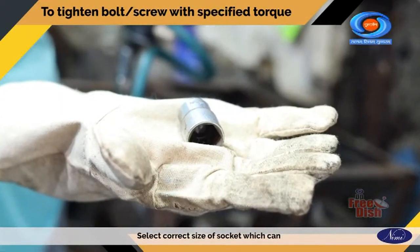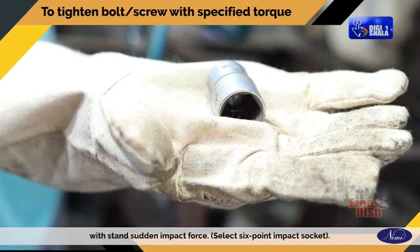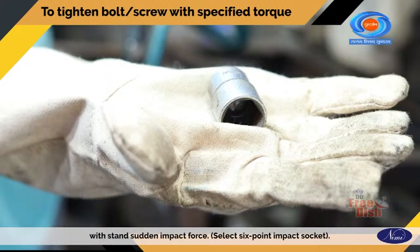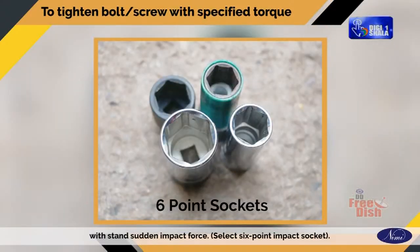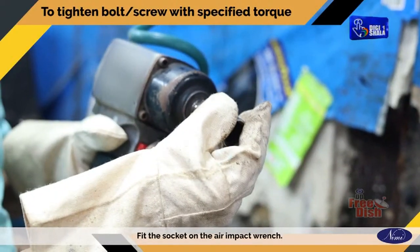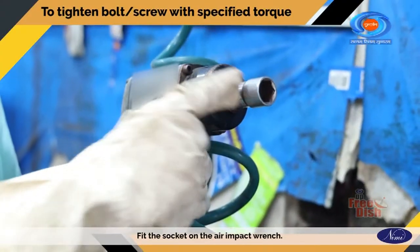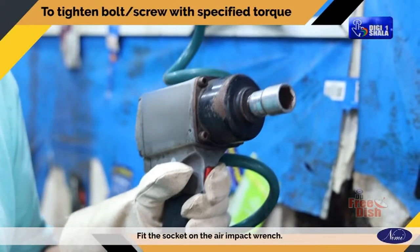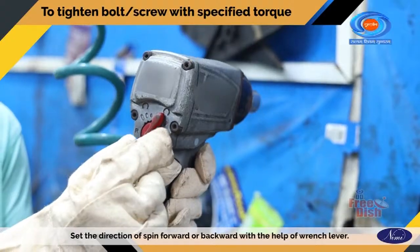Select the correct size of socket which can withstand sudden impact force. Select a 6-point impact socket. Fit the socket on the air impact wrench. Set the direction of spin, forward or backward, with the help of the wrench lever.